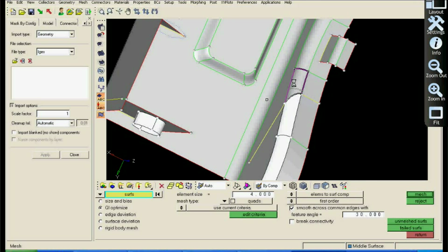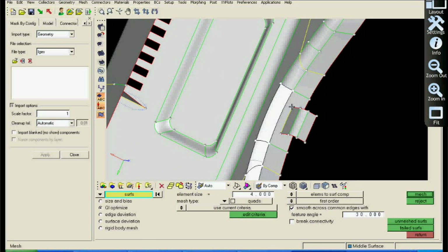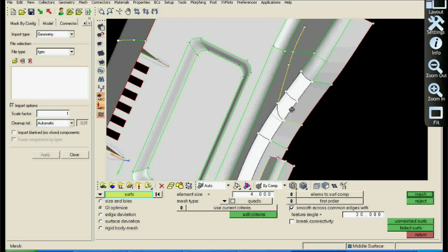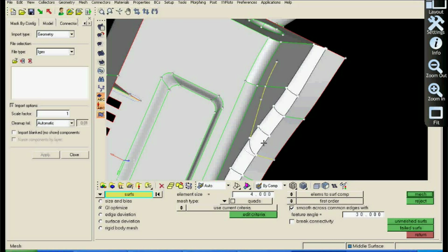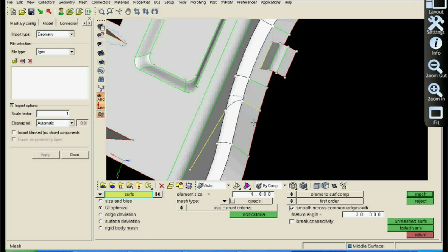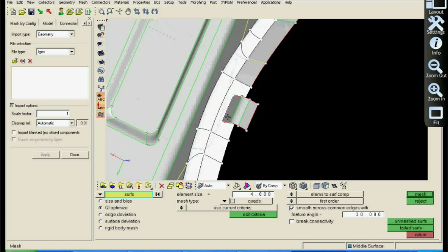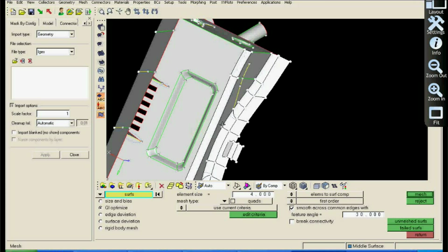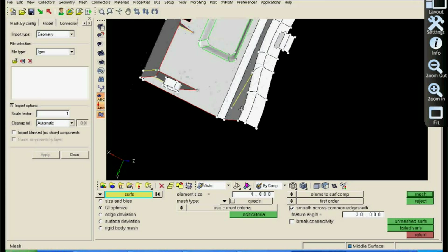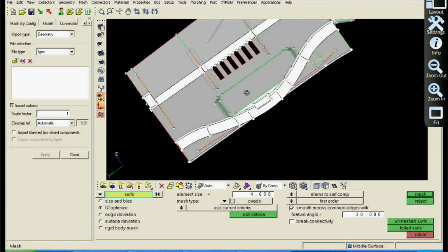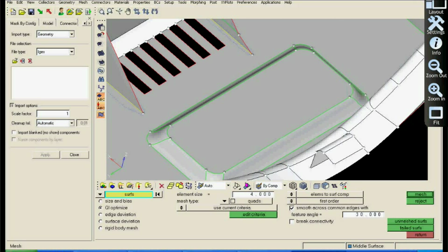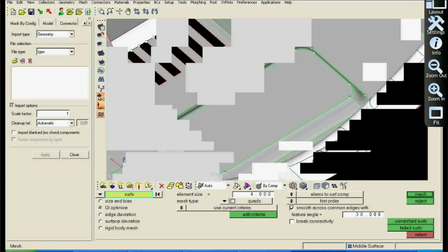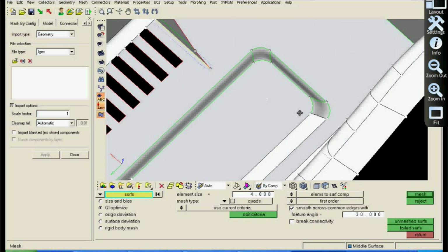These are the areas which I have already highlighted, and I just want to show you that this is where I want to focus, because these are more or less easy square plates where we can have a map mesh easily. So that is why I am keen to have a map mesh in this area. And generally, in most parts, radii are the areas where we can have high stresses, depending on the part and kind of loading.